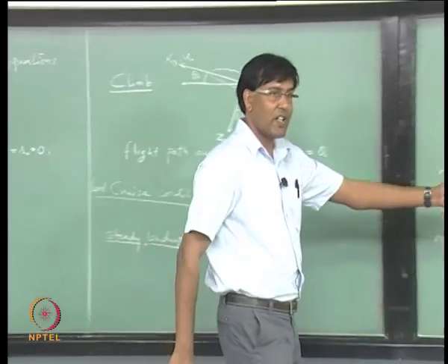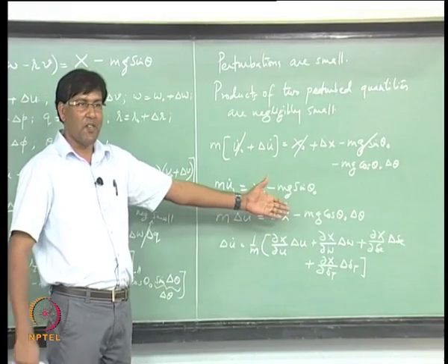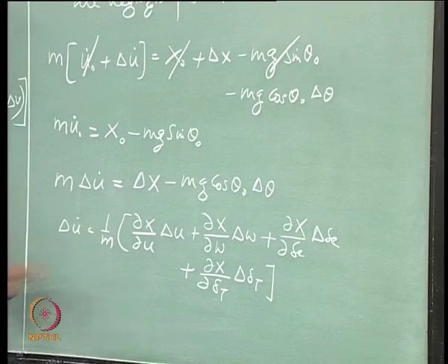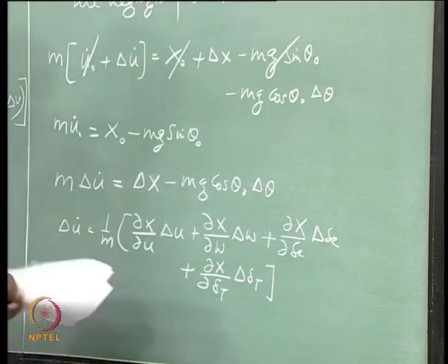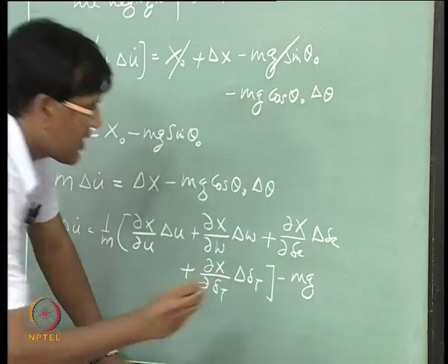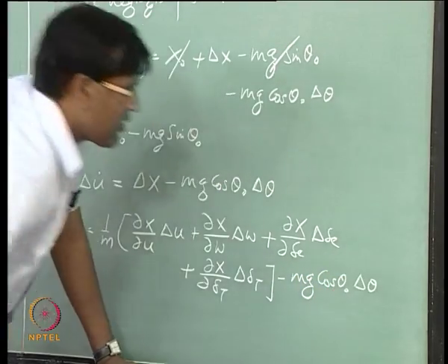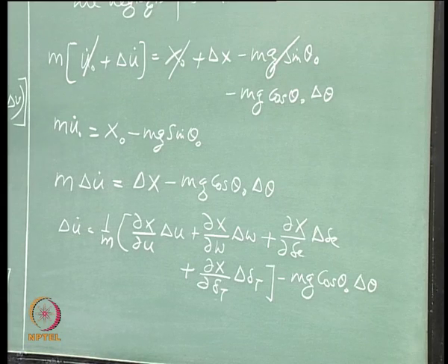If it affects, you should include that. You can have another term here. We will assume that this force is not being affected by the perturbation in side velocity in the pre stall flight regime.